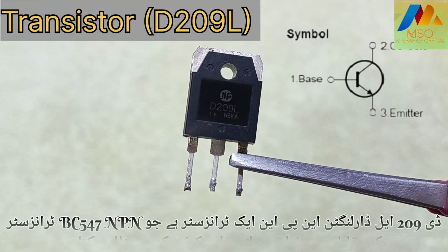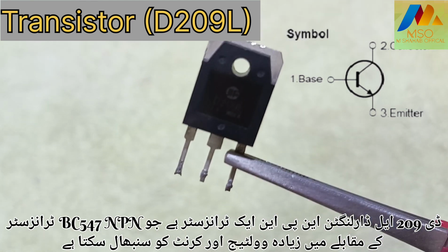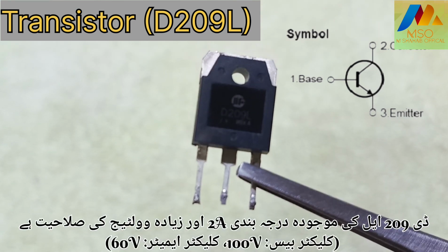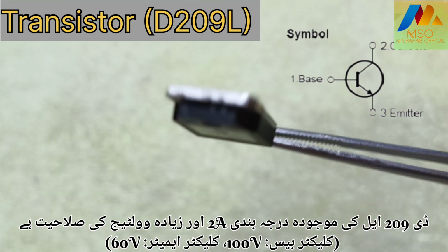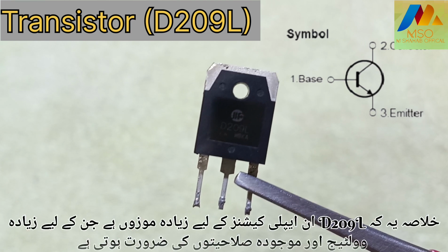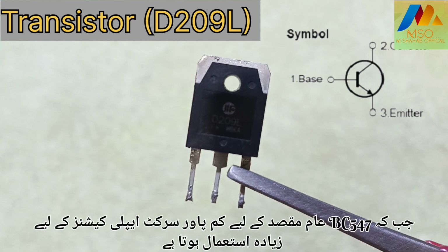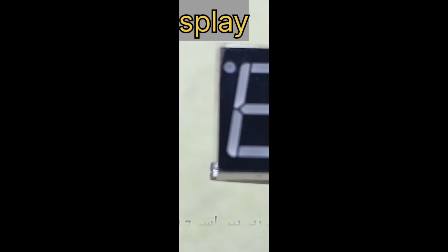The D209L is a Darlington NPN transistor that can handle higher voltage and current compared to the BC547 NPN transistor. The D209L has a higher current rating of 2A and higher voltage capability, collector base, 100V, collector emitter, 60V. In summary, the D209L is more suitable for applications that require higher voltage and current capabilities, while the BC547 is more commonly used. Now what you see in the video is called a 7-segment display, and its symbol is something like this.